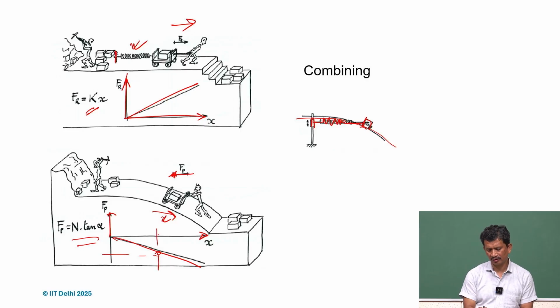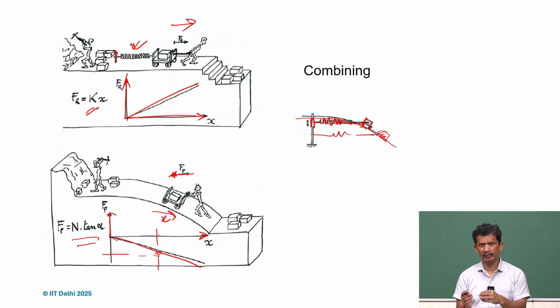It means we can place it anywhere and it will stay there, because the forces from the positive and negative stiffness balance each other, and that's why it's stable at every location. This can be very good because we can combine the positive and negative stiffness parts and tune the overall stiffness of the system.